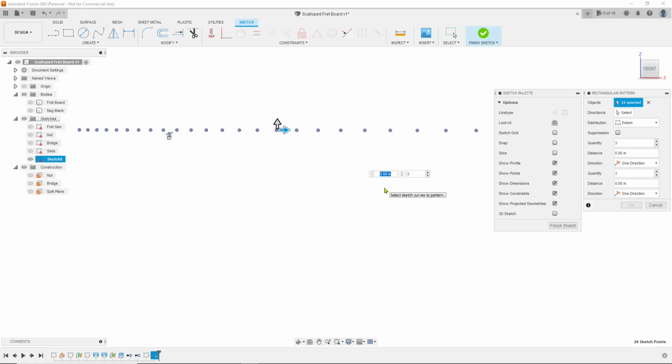So just for instance, say they were 1.05. I want to add a little bit to both sides so that my fret edges aren't dangling over the scallops into the abyss. You want a little bit of wood exposed on both sides of the fret, so I'm just going to say 1.1 or 0.11. So half of that will be 0.055. So 0.055 is that distance.